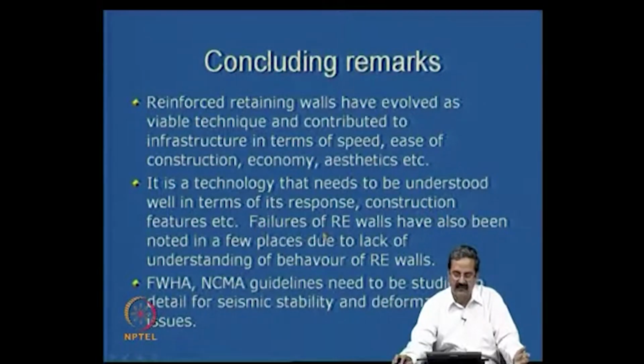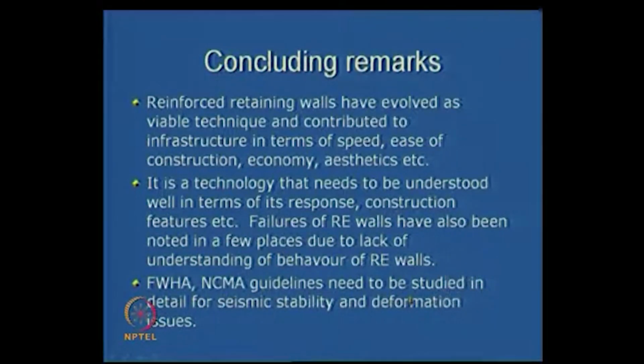As I said, failures of RE walls have also been noted in a few places due to lack of understanding of the behavior of RE walls, because people feel that it's a somewhat easier system. Technically, it's a very nice and elegant technique, but the implementation needs to be a little more careful, and of course the guidelines are excellent in this, and one needs to understand them properly. As I said, Federal Highway guidelines are there, NCMA guidelines are there. They need to be studied in detail for many of the installations.